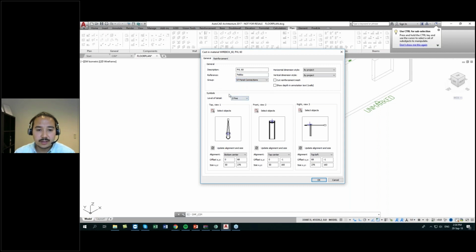The level of detail shows how the custom material is shown. If we're seeing the element in 3D in Solid, then the 3D view will be used, if there is a 3D view, of course. Fine is used when we have it in wireframe, and usually we have it in wireframe, so we don't use unnecessary computer memory and CPU. So as often as possible, we have it in wireframe.